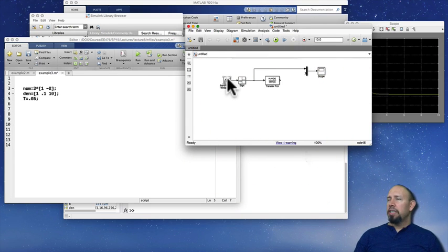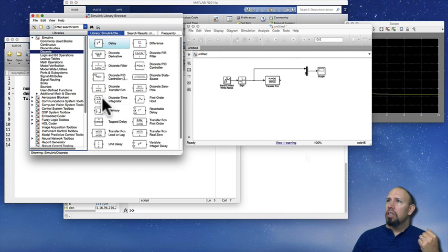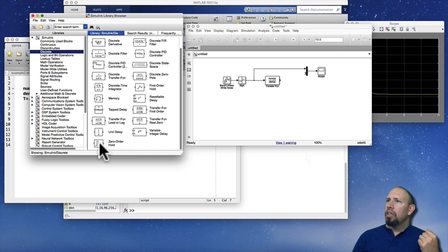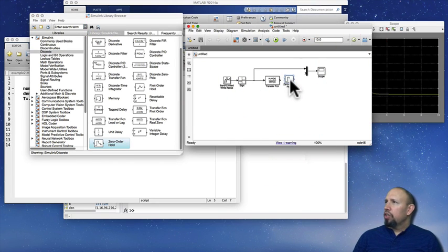So this is basically going to give a random sequence that changes every T seconds. And then I put it through this sine function, which converts it into a random binary sequence like we saw before. I'm now going to go to Discrete and pick a zero-order hold, which acts like an analog to digital converter, so that these are both discrete time signals. They go into a mux, which combines two signals into a single signal that now goes into our scope.